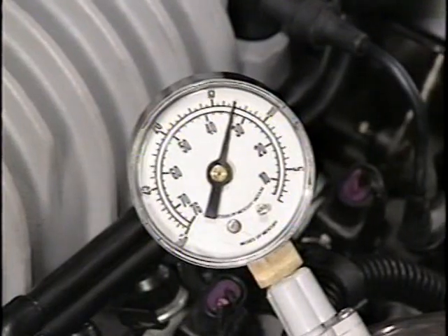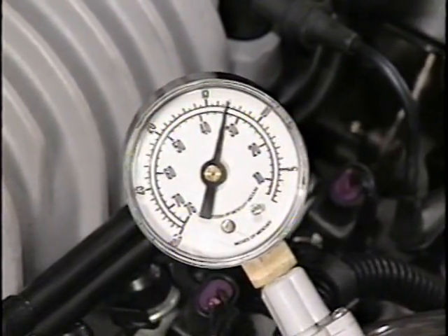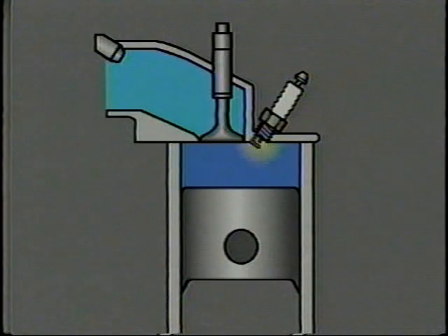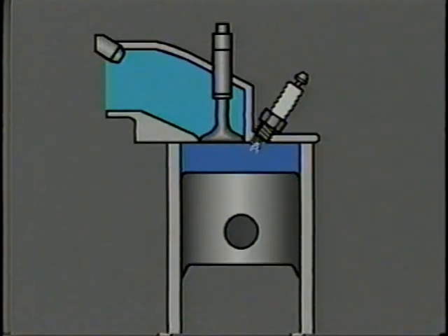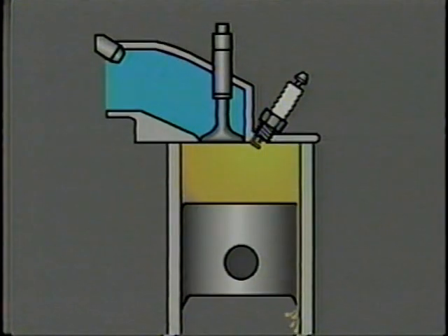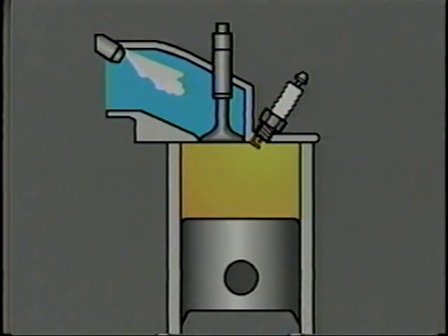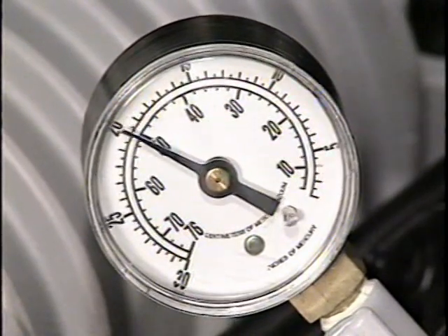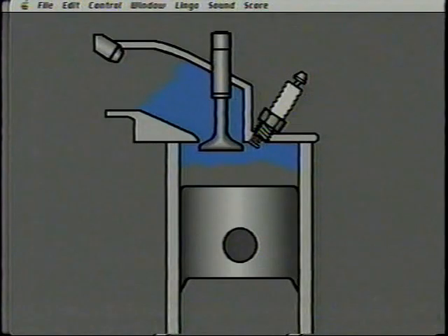If you see a low but steady reading, it may be caused by late ignition timing or valve timing that is incorrect. A low but steady reading can also be caused by leaking piston rings or a leaking intake manifold gasket. If your vacuum signal floats or drifts, it may be caused by an extremely rich or extremely lean mixture. If your vacuum testing suggests a problem, it means more comprehensive tests. Tests like a cylinder balance test must be performed to pinpoint the exact problem.